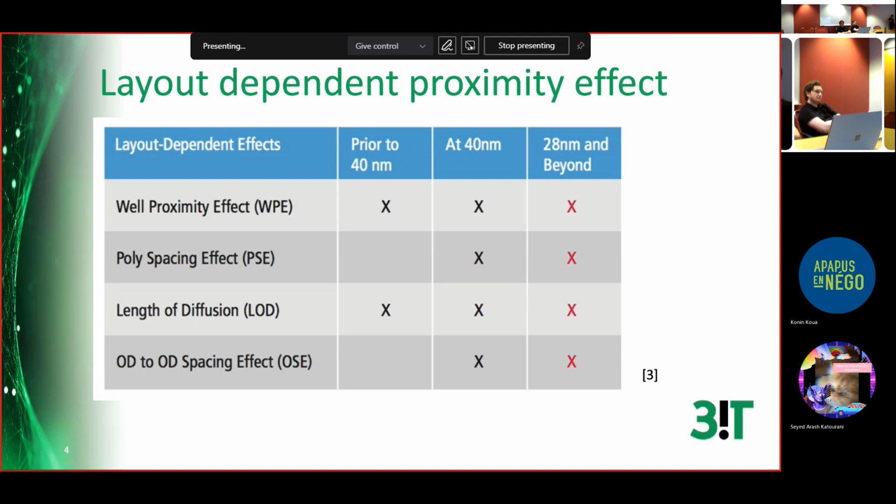Between two polys, for example, here, if I draw this one, this is two polys of two fingers? Yeah, two fingers. Even just for parasitics, you can see there is a different impact because they are closer, there is more coupling, and this is even worse with FinFETs. So how should you solve that problem?